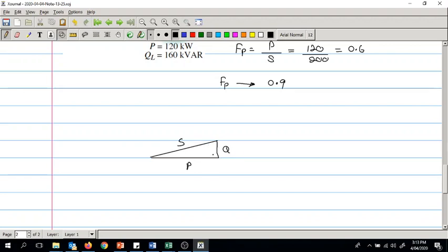Well, for the calculations here we need it, but we are more interested in the resultant power factor, that is PF to be 0.9, which is cos theta to be 0.9. Cos theta is P over S. Now for that we have to calculate our new S as well.